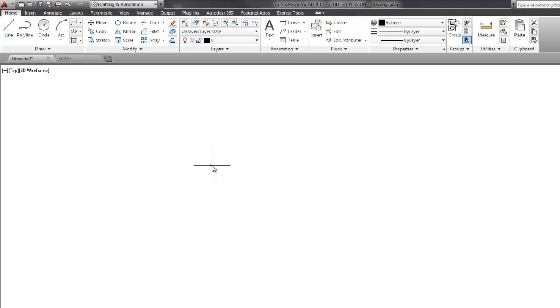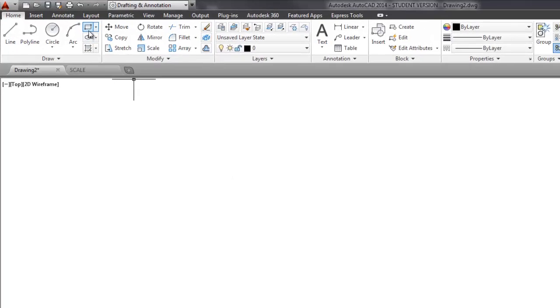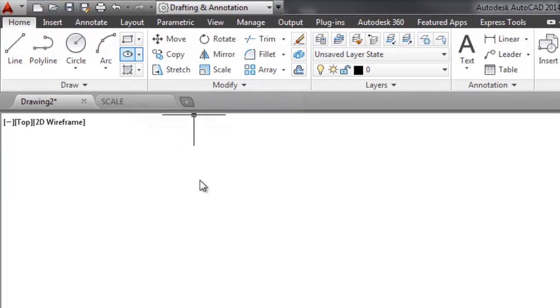Today we're going to work on some more drawings, trying to use some of the things that we've learned to build upon that. I'm going to start off with doing the rectangle command. There's an icon up here in the draw menu, that is the rectangle. I highly encourage you to use the keyboard commands, which would be REC. Before I leave that, there is a polygon hiding underneath that rectangle, just so you know where that is.